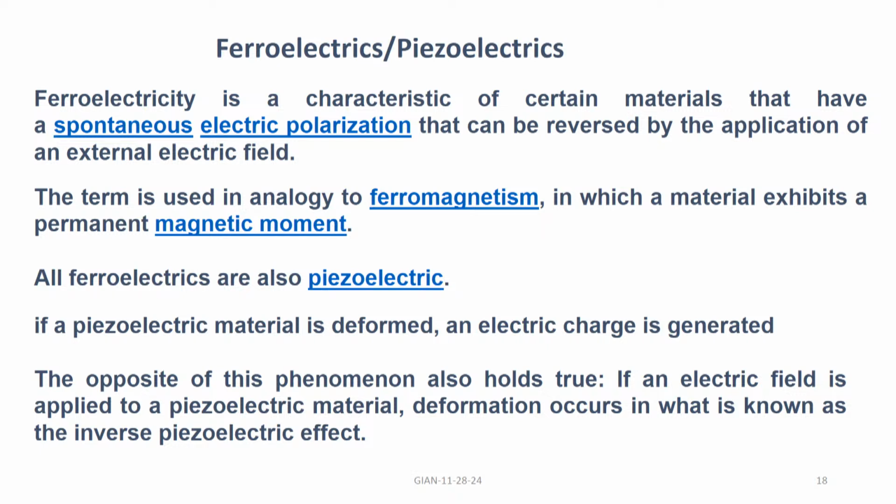reverse the polarization or realign the ferroelectric domains in the ferroelectric. And piezoelectrics, they are not ferroelectrics. Almost all materials are piezoelectric in the sense that if you apply an external electric field, there will be mechanical deformation, such as quartz or aluminum nitride. These are not ferroelectrics, but they are all piezoelectrics, because there is always a change in the charge configuration that will lead to a dipole moment under an external electric field.